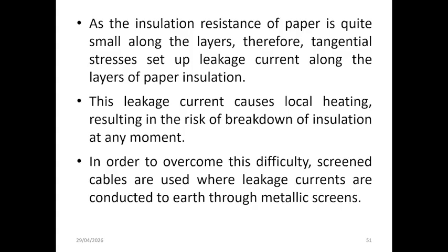So these leakage currents lead to local heating, which increases the risk of insulation breakdown. To avoid this problem, screen cables are used, where metallic screens safely conduct leakage currents to earth, improving reliability and safety at higher voltage levels.